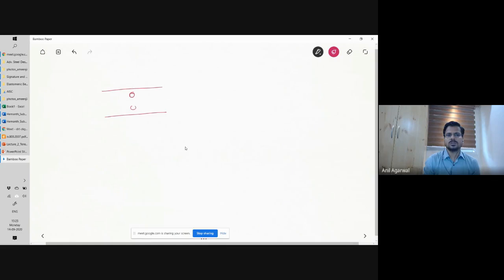If we have two holes and the load is acting in this direction, then the two holes are aligned so that they pass through the same perpendicular line, that is, in the direction perpendicular to the load. Then of course it will be B minus 2D times T, correct?